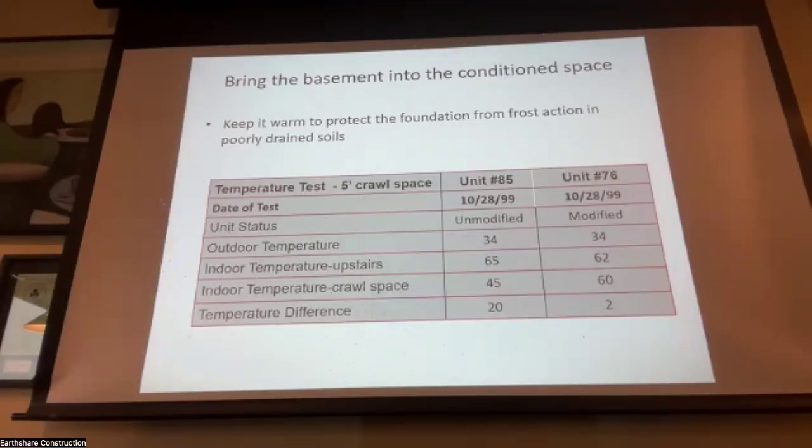We did a job for Building Science Corp. and they did all these calculations. We did what I call the Abbott system, air vapor insulation and drainage system, with the vapor retarder from 1 foot below grade down and the foam from there up. Building Science had like 10 different contractors with 10 different systems do the foundations of a big complex of buildings. Same one building, but lots of different basements. And they said that the Abbott's AVID, air, vapor, insulation and drainage, won.